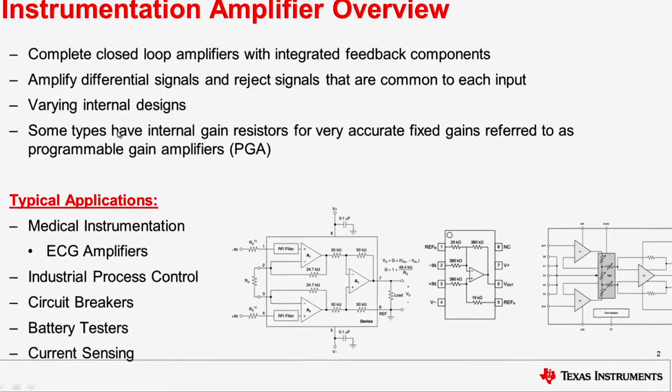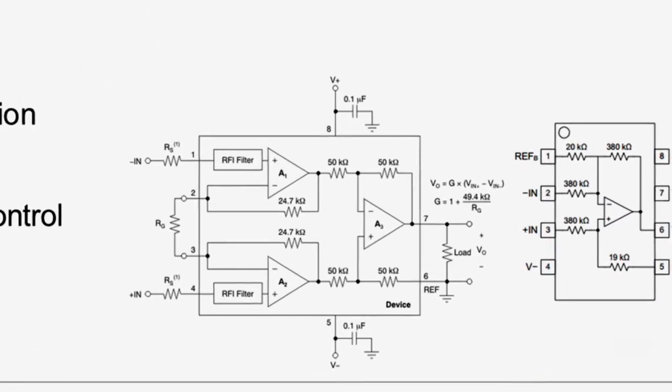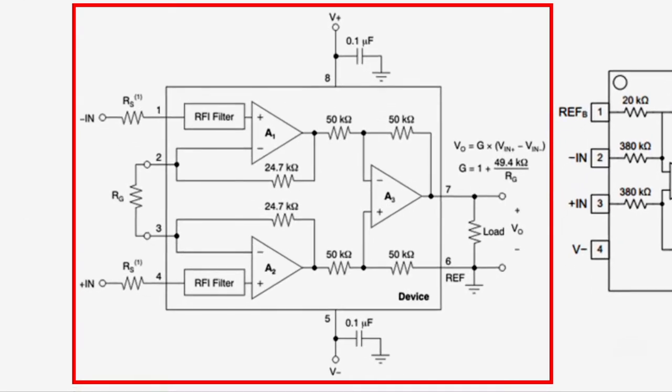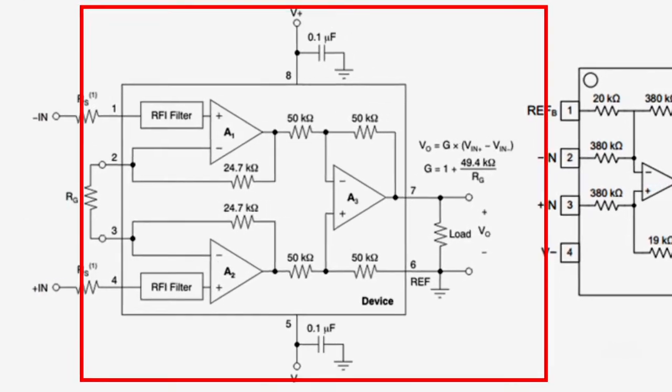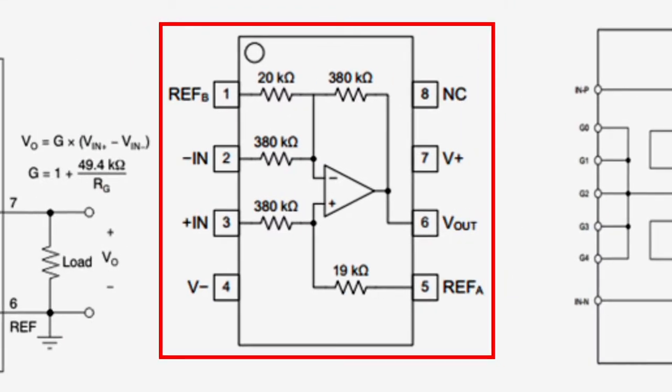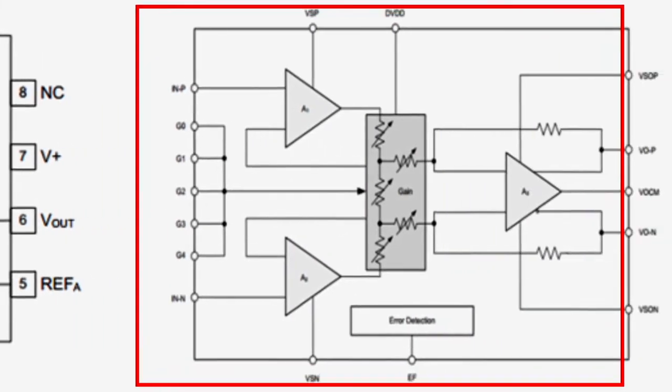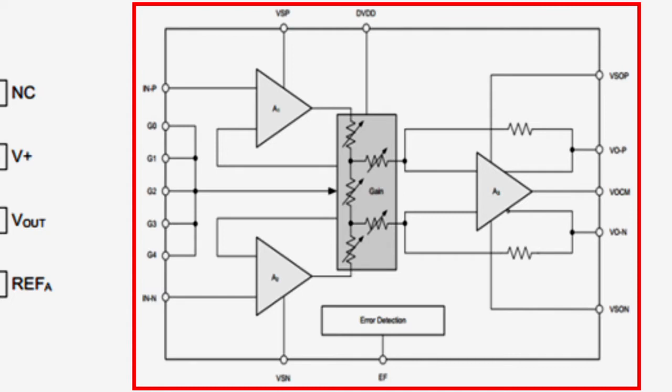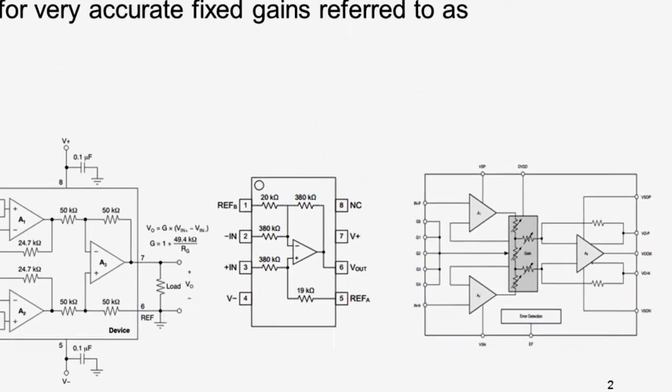in your application. TI's INA prefix covers instrumentation amplifiers such as the popular 3-amp INA, difference amplifiers which use a simple topology of 4 or 5 resistors around an amplifier, as well as current sense amplifiers which aren't shown here but are specific to current monitoring applications. There are also programmable gain amplifiers, or PGA, which have the gain options internal and can be digitally controlled. These all have similar functionality but can vary vastly in characteristics.